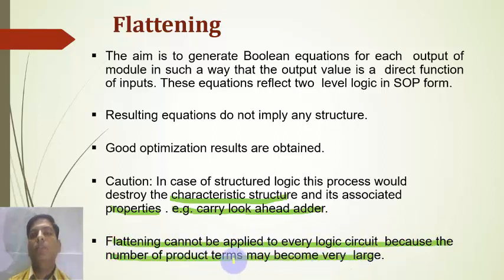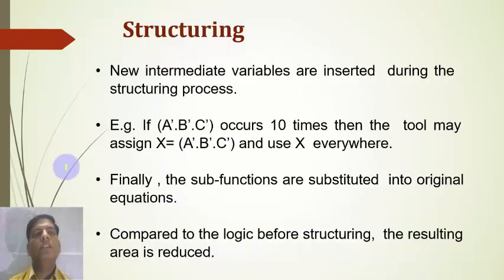Flattening cannot be applied to every logic circuit because the number of product terms may become very large. Structuring. New intermediate variables are inserted during the structuring process.